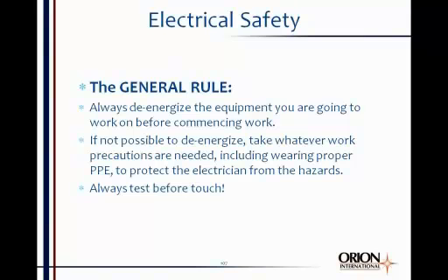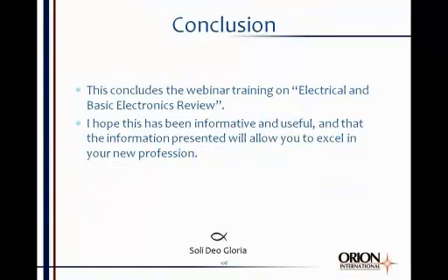General rule in industry now is de-energize the equipment unless there's no way you can work on it. And troubleshooting is an exception, of course. A lot of times you have to leave the equipment energized to troubleshoot. But if there's any way you can de-energize it, that's the expectation. If you can't de-energize it, you've got to do whatever it takes, including wearing the proper PPE, to protect yourself from the hazards of the job. And always, always, always test before touch on anything that could be energized.